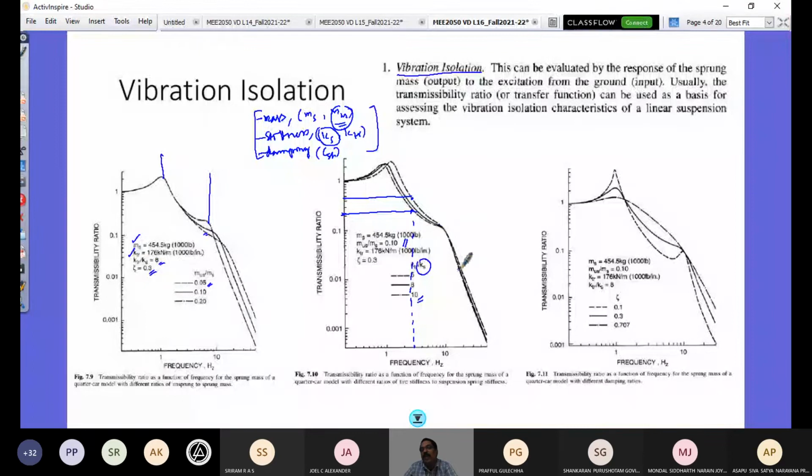It is not a high damping value. High damping value is of course needed to account for the region near the natural frequency of your sprung mass. But apart from that, you see the value is not favoring. So the one with the lighter damping, 0.1, is favored in the mid frequency range as well as the higher frequency range as far as transmissibility is concerned.